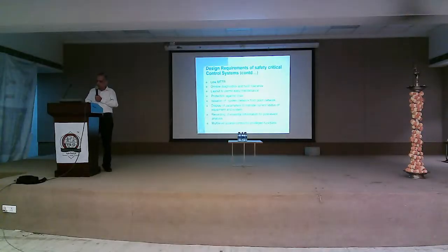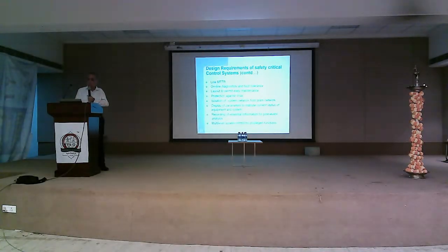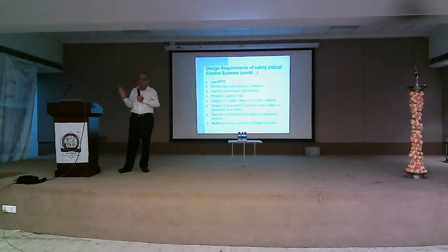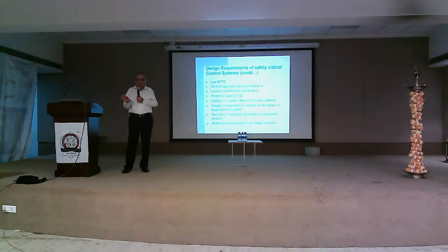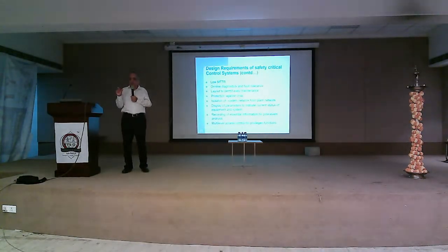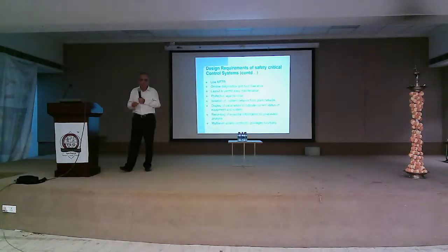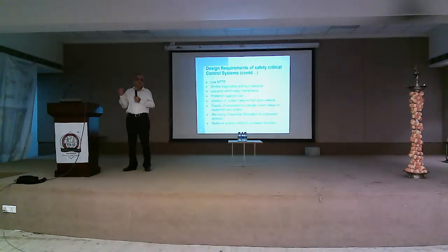Online diagnostics and fault tolerance I have explained. Layout to permit easy maintenance so that any board can be removed anytime. Protection against virus: it is an embedded system. The software is in an EEPROM covered with black coating, so there is no chance of virus entry.